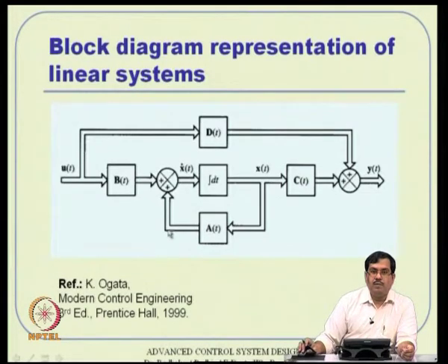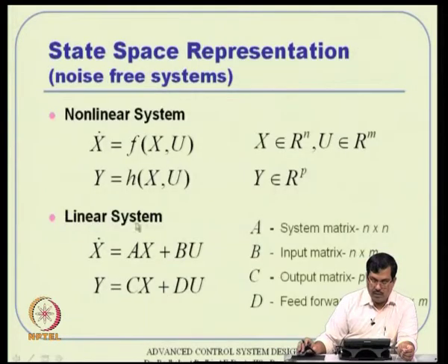Okay. So, what is happening here? Let us construct this x dot. If I start from this integration loop, there is x dot. Remember, these are a set of integrators, so x dot comes in component by component and goes out component by component. I collect this vector and then collect this vector as well. Now, once I have x of t, x dot is what? x dot is Ax plus Bu. So, I will construct x, pass it through A, then add it up. There is an Ax component coming here, then there is a B and a u, so the Bu component comes here. So, x dot equals A times x plus B times u, and that is constructed.